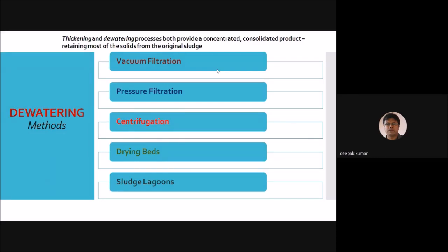Different industries use different processes for dewatering. An industry can adopt vacuum filtration, pressure filtration, or centrifugation, based upon the density or the type of sludge present. Vacuum filtration for dewatering sludge uses a drum over which is laid a filtering medium consisting of a cloth of cotton, wool, fiberglass, plastic, or stainless steel.